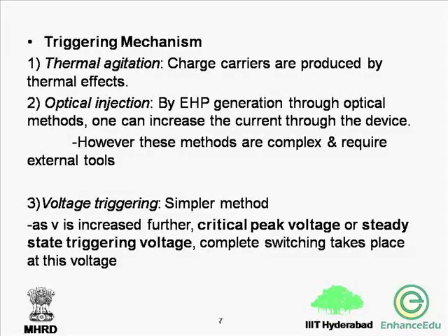In this configuration, the base of the PNP forms the collector of the NPN and the base of the NPN forms the collector of the PNP. Thus, the base current of the PNP equals the collector current of the NPN and vice versa.